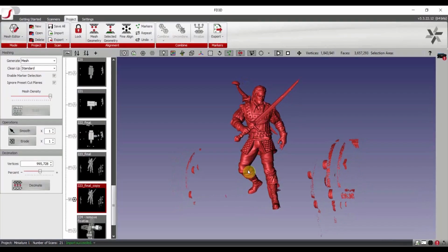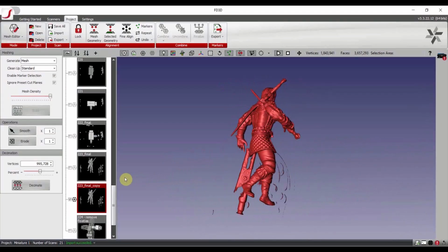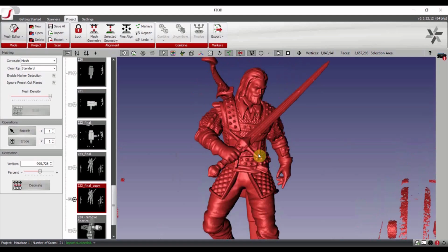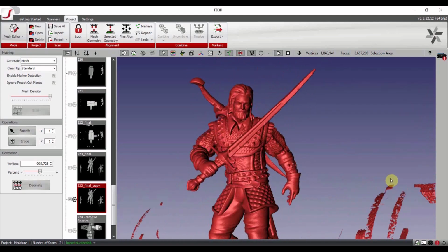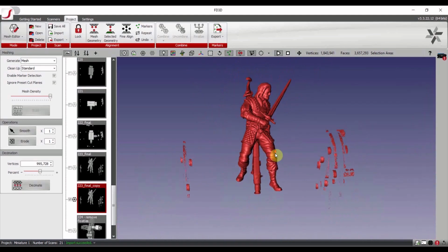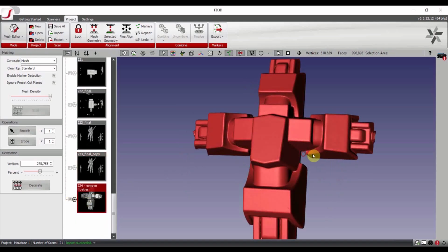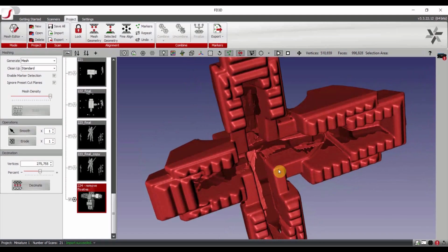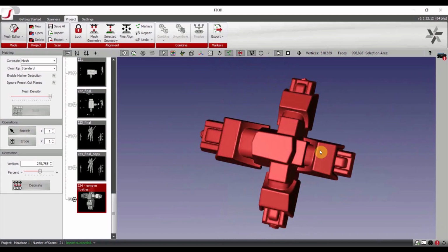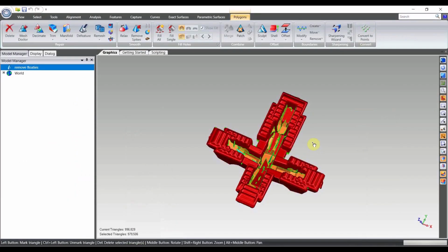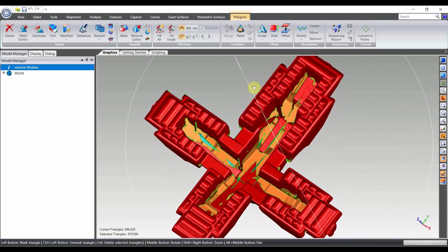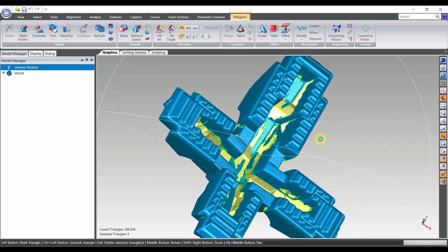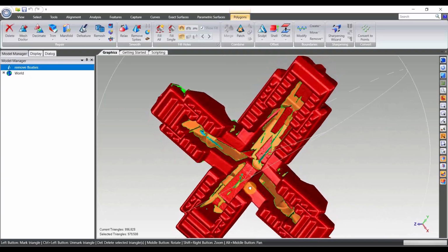Hi everybody. In this video I want to talk to you about floating artifacts in the 3D scan data. There are many reasons to see such floating artifacts on the scans. For example, when we are scanning, a part of the rotary table or part holder is scanned too. Or if the object is so glossy, the light reflection can cause some floating artifacts. So, let's see how we can remove floating artifacts easily from scan data.